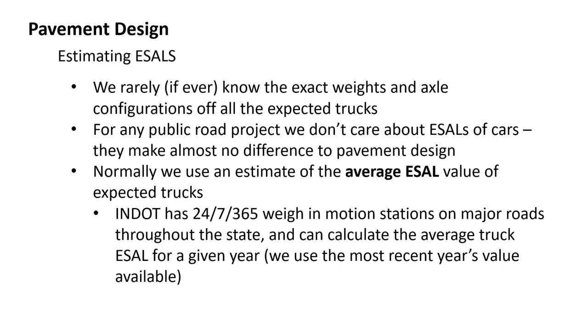And so getting your pavement set up right and figuring out what your depths are going to be as early in the design process as possible is good, because then your estimates are going to be much more accurate as you go through. All right. So, if you were to make a mistake on the ESALs, you may be showing 10% more asphalt than you need. Your client may freak out like, oh, this is going to be more expensive than I thought. I don't have enough money. We have to stop, and so forth. And that does happen.